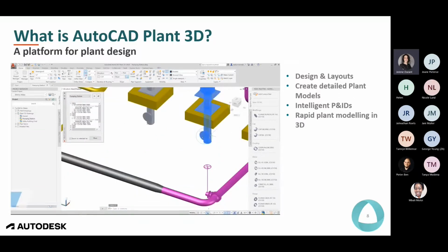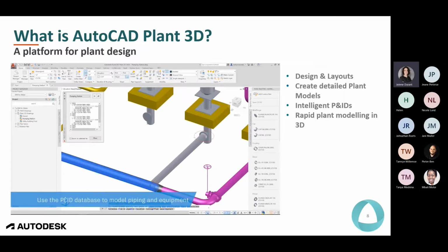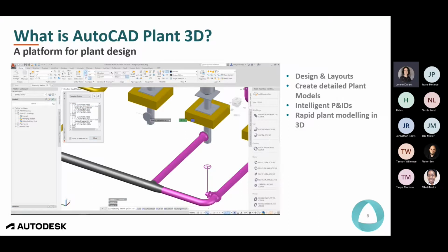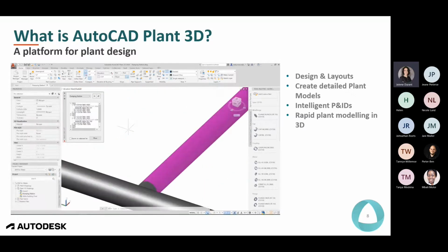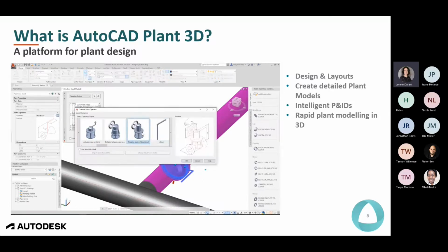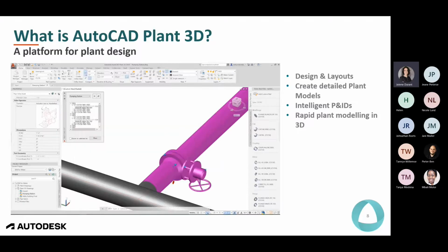pipework modeling. In the 3D model, we can add piping directly using the available modeling tools, or alternatively by accessing parts from the P&ID line list, which automatically transfers the piping specifications and catalog. Pipe connections such as mating flanges and reducing tees are handled automatically, and additional piping parts such as valves can also be drawn from the database via selection from the line list and can be modified at any time, as